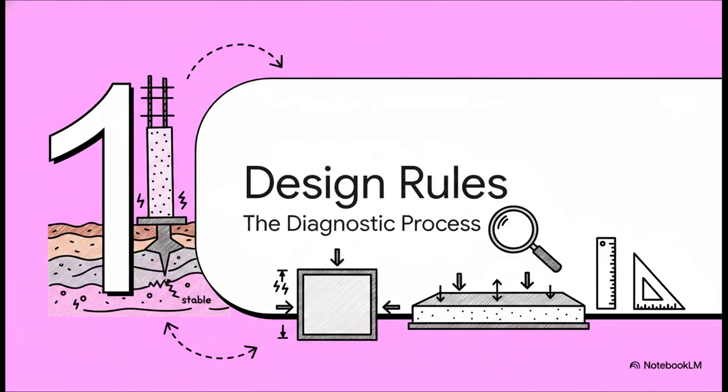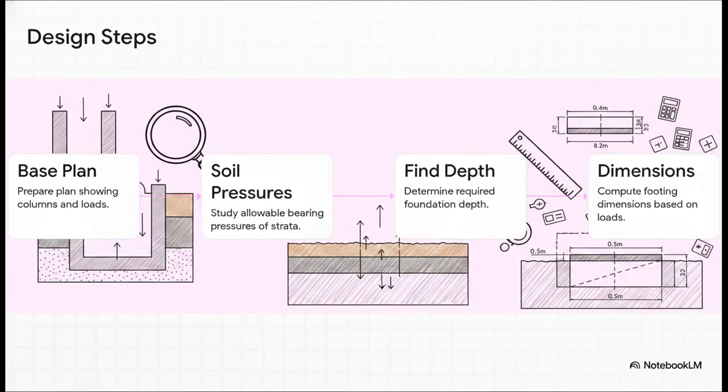Rules of foundation design, the diagnostic process. Engineers don't just guess out there. Their process is strictly chronological. Step 1. Prepare a base plan showing all columns, load-bearing walls, and estimated loads. Step 2. Study the allowable bearing pressures of the soil based on detailed geotechnical reports. Step 3. Determine the depth of the foundation.